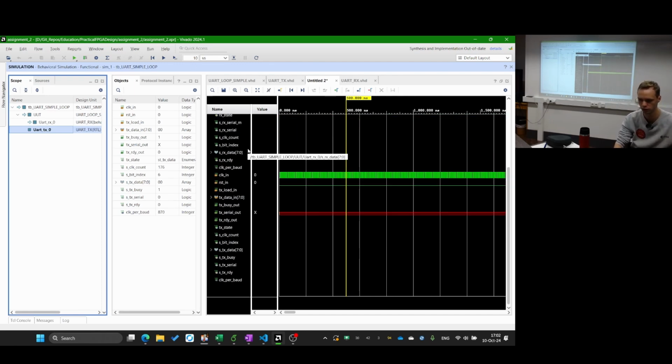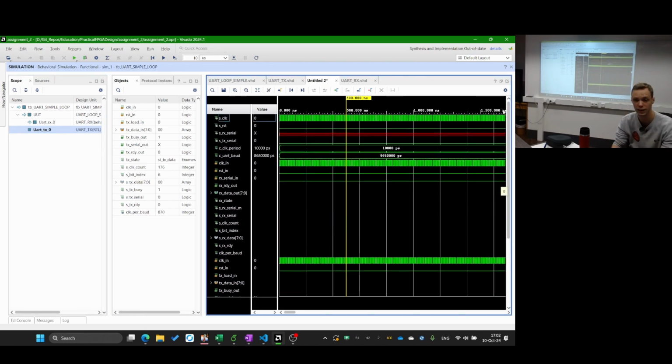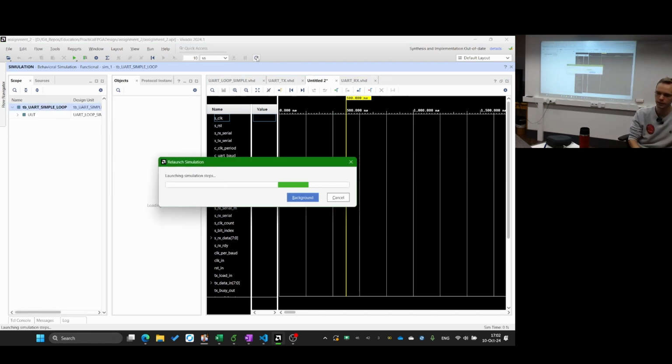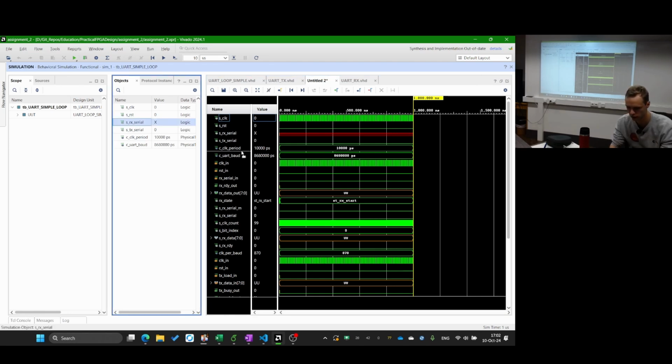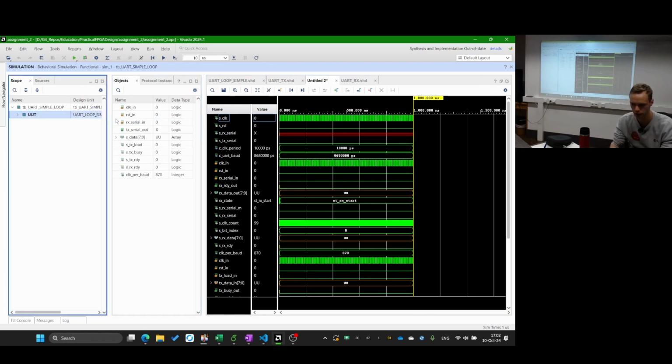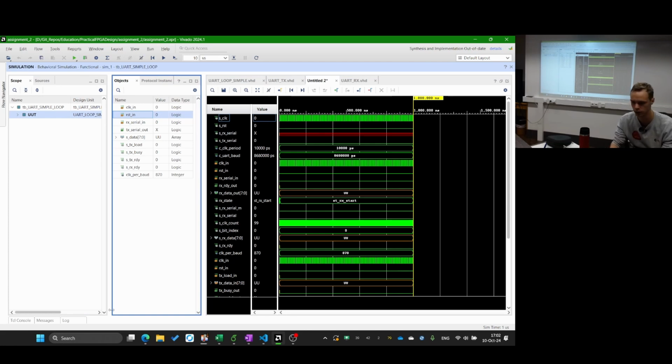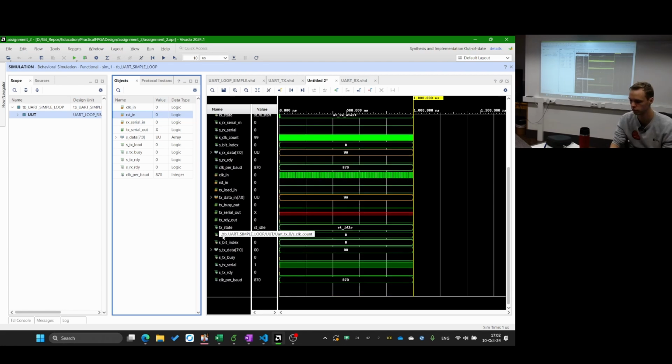And this might not show me the signals right now because I've not logged them. They are simulated, but they are not being logged. Just the results of what I see here are being logged. So I can just relaunch the simulation, and it will run that automatically, and it will show me then all these signals. And that's where we have my other signal values, which I wanted. And of course I can also open up a block and then drag a single signal. I don't have to do that block by block. There are also ways to write scripts for this, which will also help you.